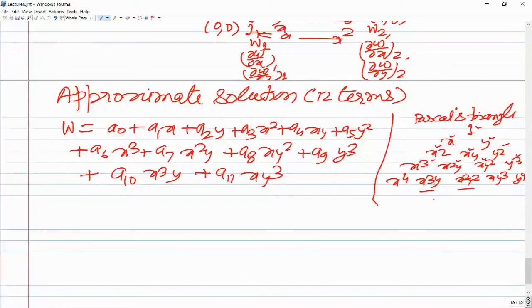To satisfy that requirement, we are taking these geometrically invariant terms. And x square y square gives the quadratic variation both in x and y, whereas x cube y and xy cube give linear variation in the other direction. So linear is given preference over quadratic. And also to satisfy the condition of geometric invariance, we need both x cube y and xy cube terms. Okay, sir.